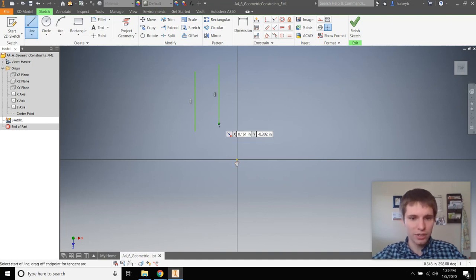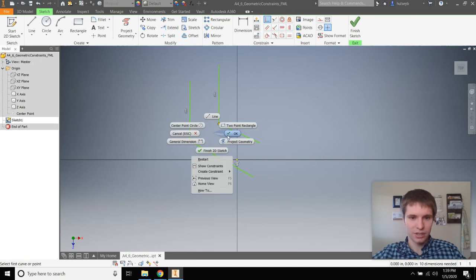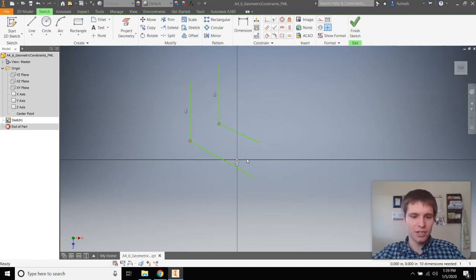So then I want coincident constraints, 2 lines connected. I can do that directly by clicking when it shows up as a green point. Or I could do it later, like say I want a line going down here, and then I change my mind. I was going to do a curve here. I changed my mind. I actually want those connected. I can do coincident constraint here and here. Okay, now they're connected.